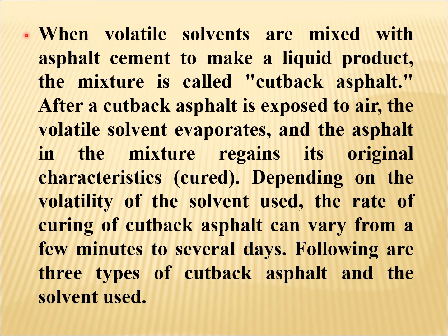When volatile solvents are mixed with asphalt cement to make a liquid product, the mixture is called cutback asphalt. So I will repeat. When volatile solvents are mixed with asphalt cement to make a liquid product, the mixture is called cutback asphalt. After a cutback asphalt is exposed to air, the volatile solvent evaporates and the asphalt in the mixture regains its original characteristics, and that is termed as curing. So we can say it has been cured.